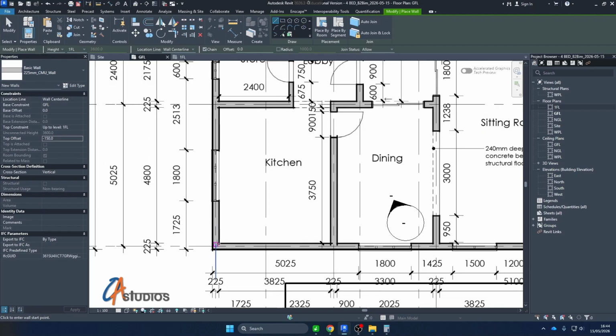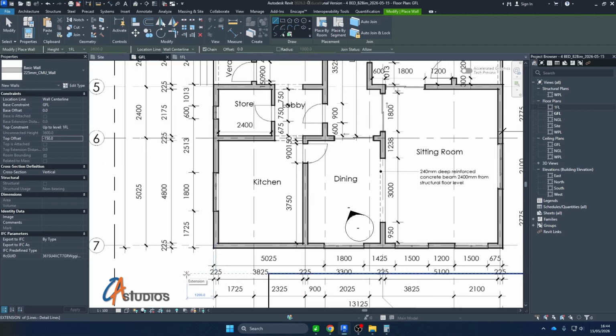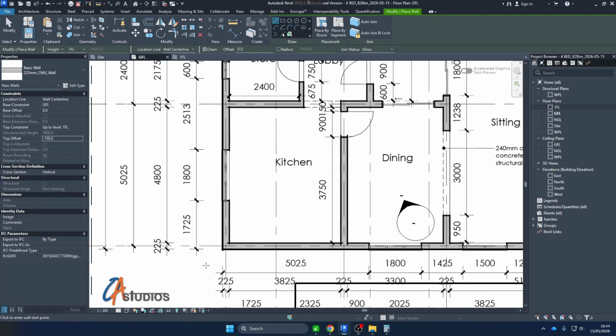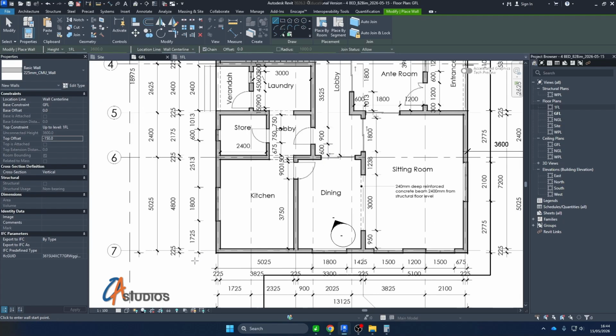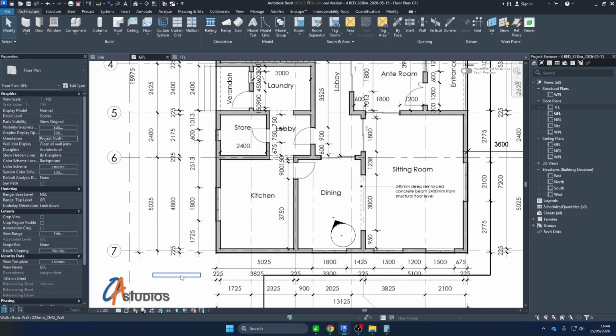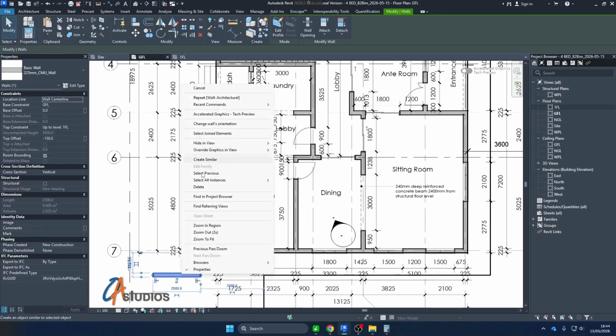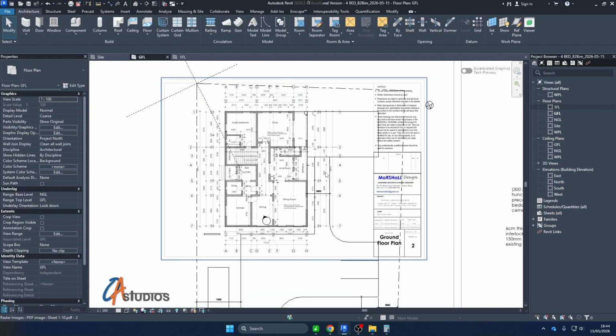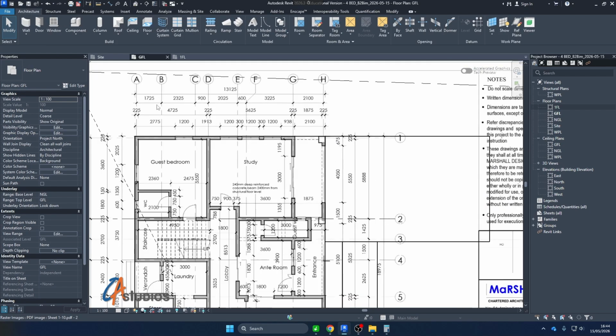What I would do, let me just draw a wall here for reference, so that I can always pick and create similar from here. But before I start drawing, I would like to create the grids so that it's easy to align.